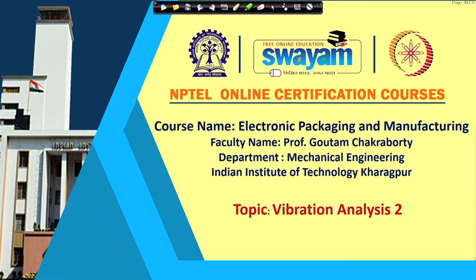In the last lecture, you learned about the importance of vibration analysis, namely vibration testing, and you also know that vibration testing is quite important from the reliability point of view. Because of vibration, the electronic component, specifically the joints, may fail due to fatigue, due to excessive deformation, or due to excessive displacement leading to the collision of the components. In this lecture we are going to learn about the basics of vibration analysis.